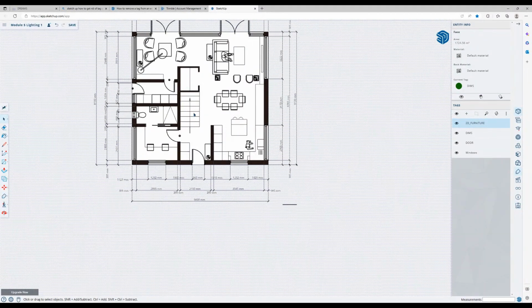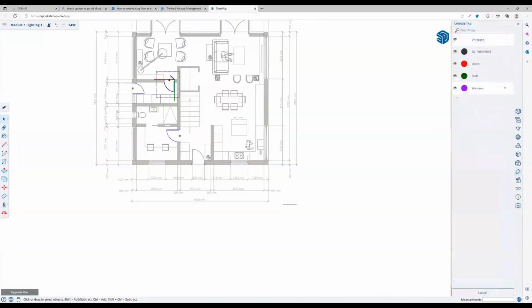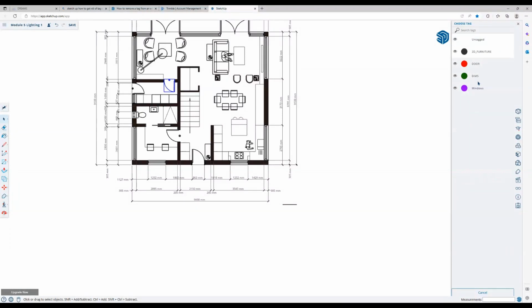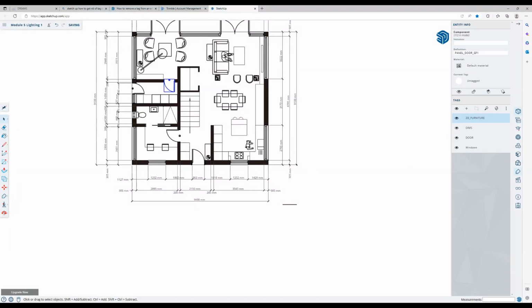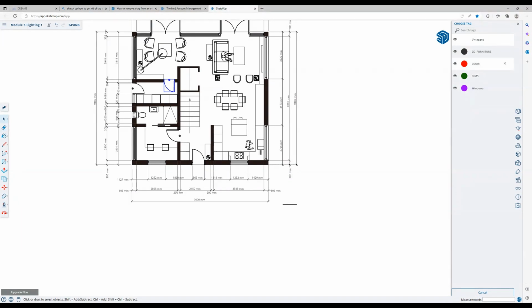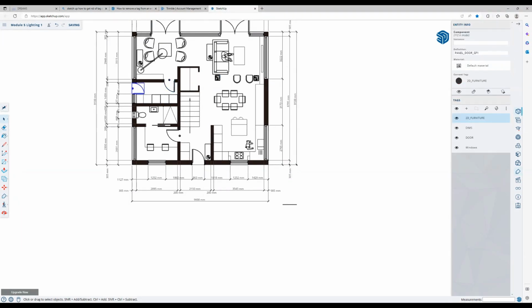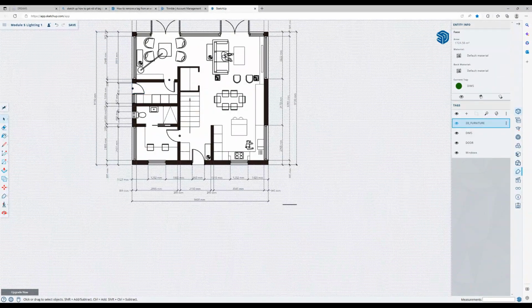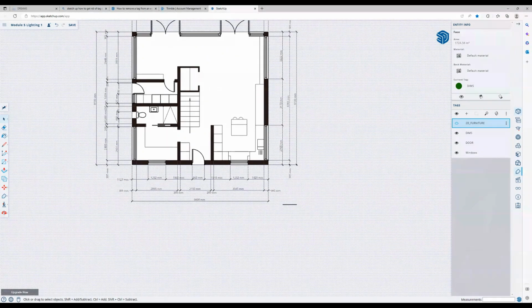Any other cabinetry I need to stay? So I've also noticed that my single doors are also disappearing. So we need to turn these into untagged. So let's click it once. The entity info, untagged. Oh, let's make it a door actually. Door. Cool. 2D furniture. Let's change it to a door. All right, so 2D furniture. Awesome, my doors remain. Okay, look. And now I've got this fully sick, empty floor plan.